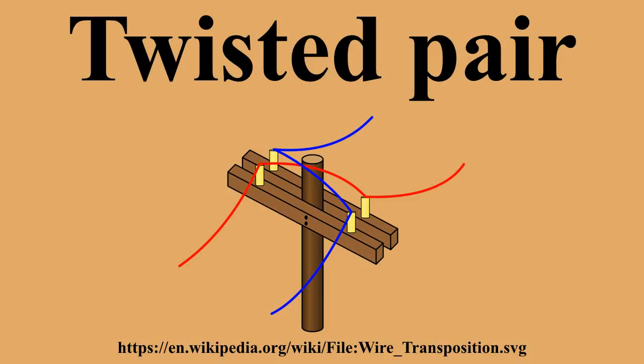Because the shielding is made of metal, it may also serve as a ground. Usually a shielded twisted pair cable has a special grounding wire added, called a drain wire, which is electrically connected to the shield or screen. The drain wire simplifies connection to ground at the connectors.